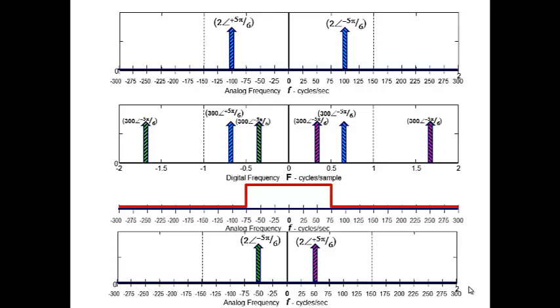And where does it alias to? Well, in discrete time frequency, it's the starting frequency minus, well, where's our equation? It's this equation, but the discrete time version, where all my frequencies are normalized by Fs. Normalized by Fs. That's capital F0. Oh, that's just an integer.